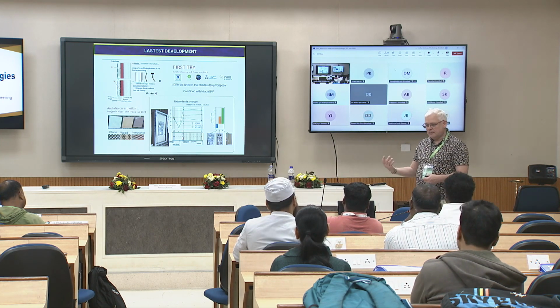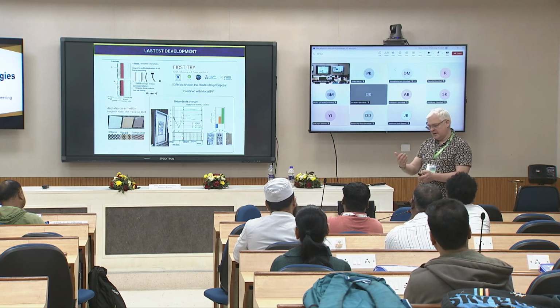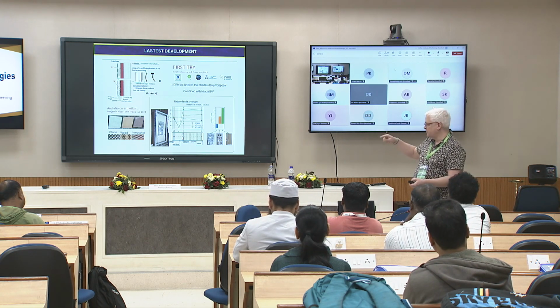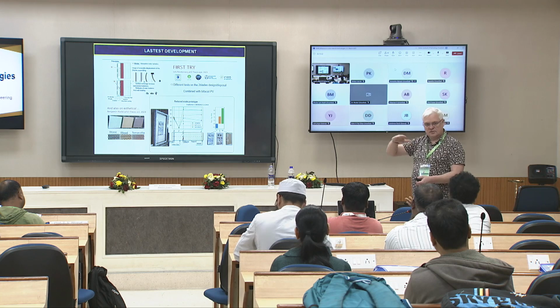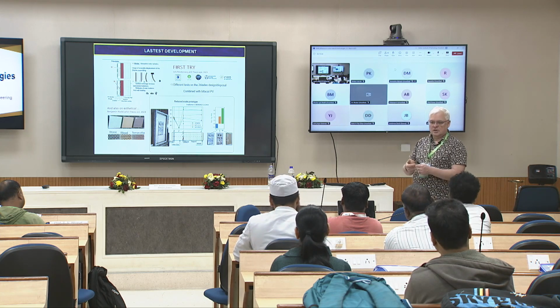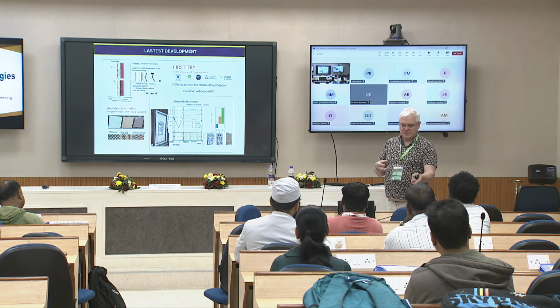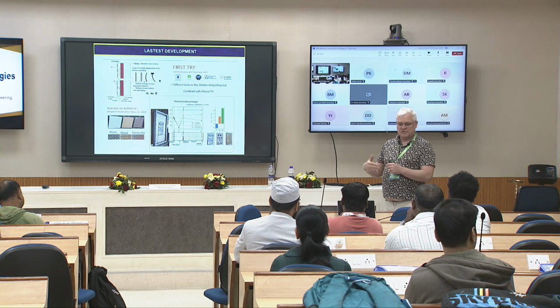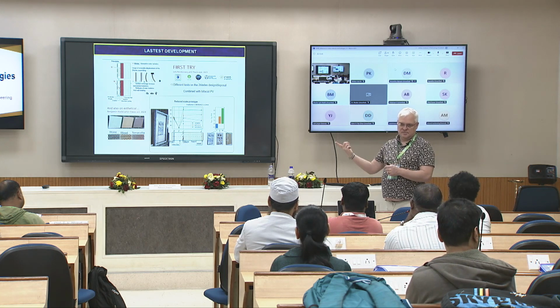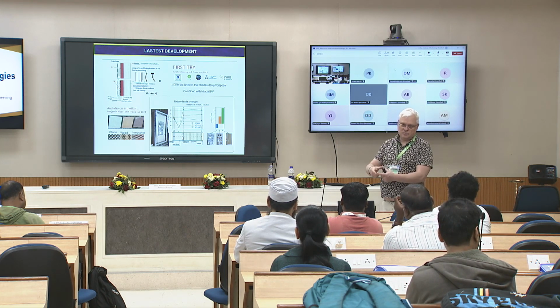So the tools that we are developing are analyzing the production, and depending on the production, I showed you some, for example, when there is shadow, there was a drop like this, so the idea is to make the link between phenomena and the impact on the PV central. And to identify, if there is that, it is because there is dust on one panel.